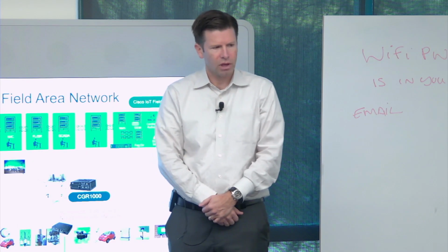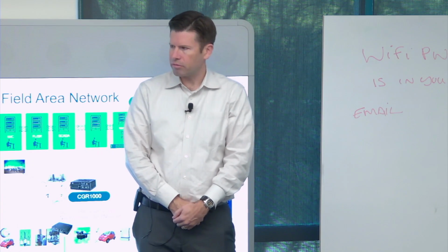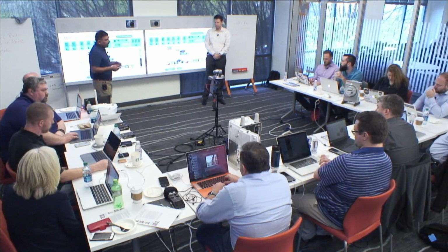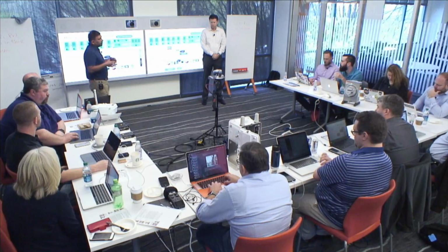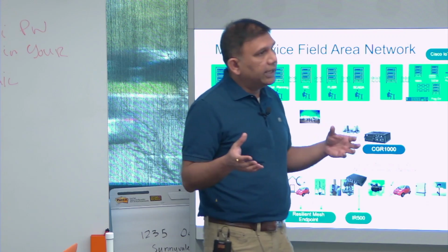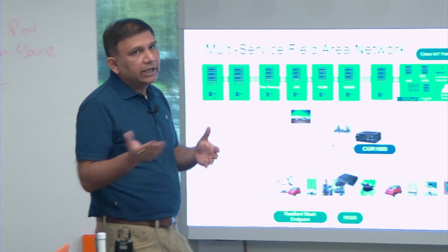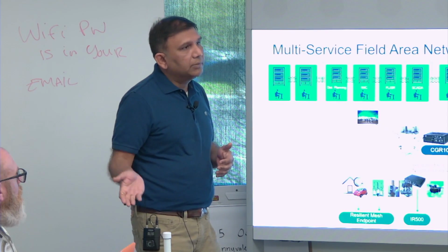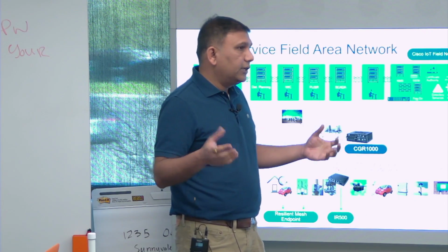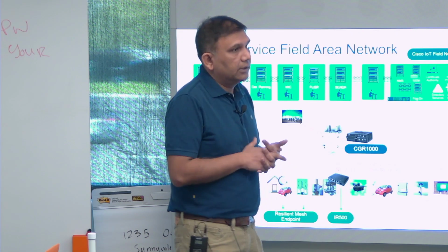How wide are you using right now? How wide is your channel? Yeah, so that depends on the modulation. I'll come to that. But if you're using FSK, you have 64 channels there. But with OFDM, which provides much higher data rates, we use a channel spacing of 800 kilohertz. And that can give you data rates from 1.2 megabits down to 50 kilobits, right? But the link budget that you get with lower data rates at such a wide channel spacing is much better. Right?